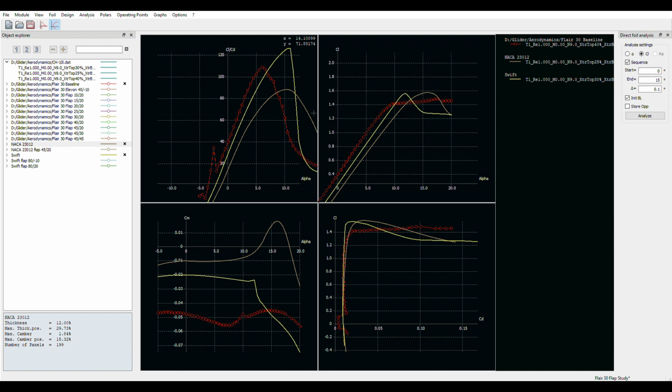And in the aggregate, on a competition day, I might be able to outclimb them and then get to the top of that thermal sooner and reconfigure for fast flight, pull the flap up and go fast and maybe win the day that way. So when you're in competition, it isn't just absolute L over D that wins the day.